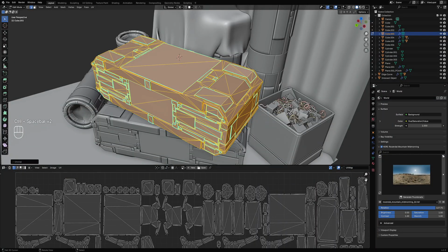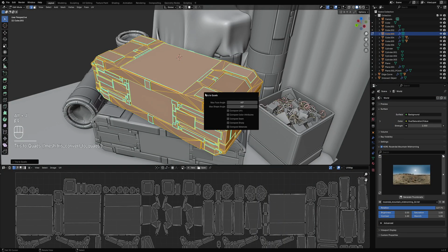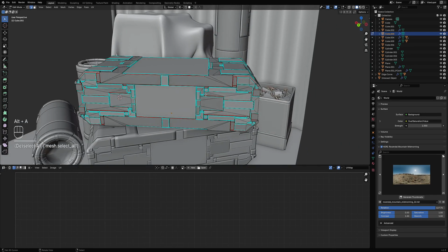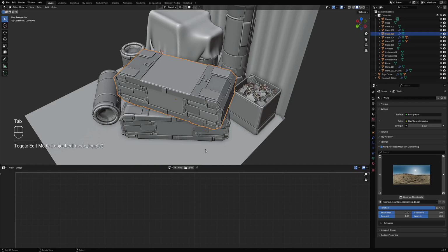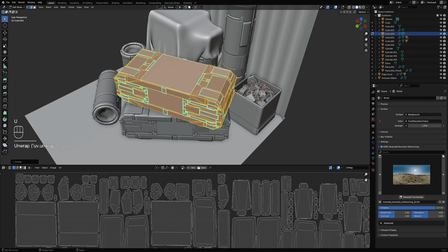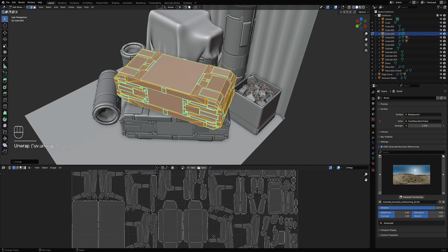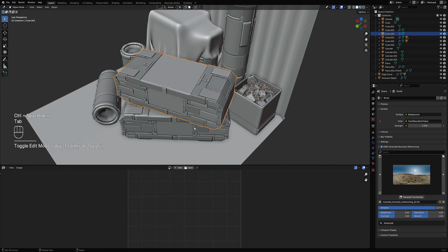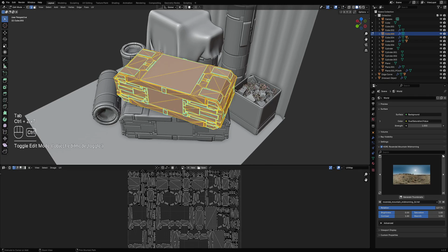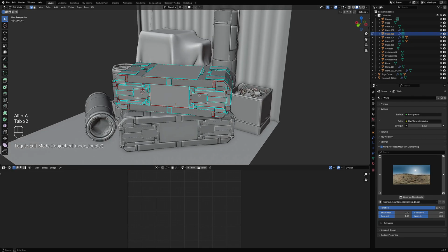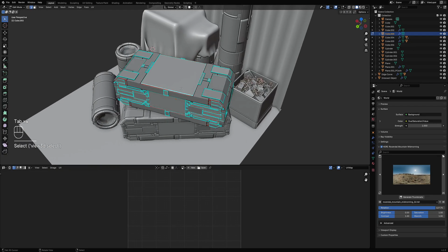So to get rid of the triangulation, you can just press Alt J and set the use it. Press F9, set this to 180. Yeah, most of the triangulation is gone, and then all you have to do is a bit of cleanup. Okay. But my advice to you is to just avoid triangulation, because the renderer will already do that, and this will not be animated anyway.